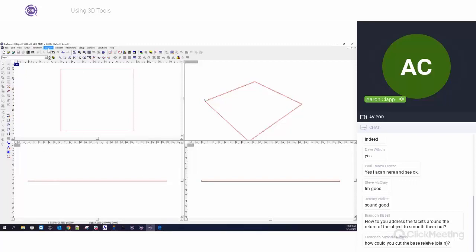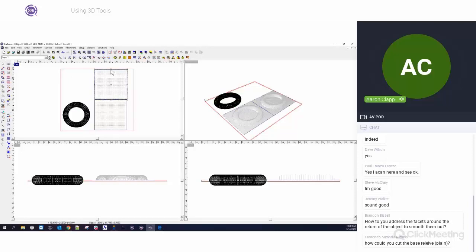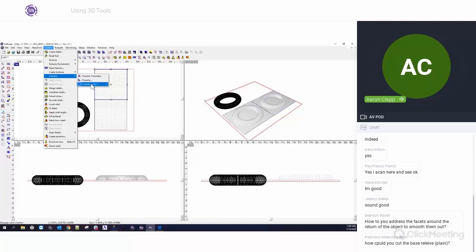So, for example, let's pull that back so that we have a 3D object. Let's go back into Chamfer. The Chamfer carve is a slightly different variation of the Chamfer. The chamfer centerline is a chamfer tool that forces it to be down the center line and has some additional properties to it. We also have some objects like spin. We also have extrude.